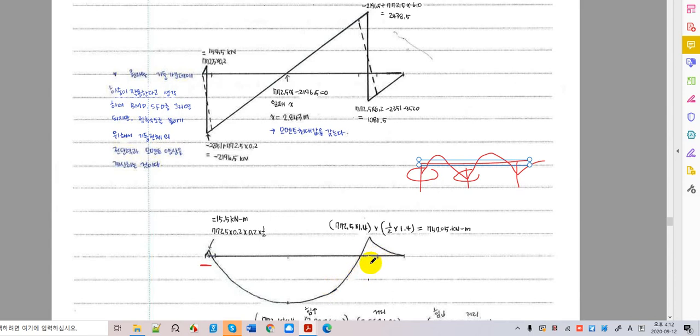Which is the bottom bar here, and the top bar? This area is the bottom bars for slabs, which is the top bar for your foundation, this part, right? If you're confused, you can just flip it over and take a look at it as a slab, and flip it back to the original foundation.